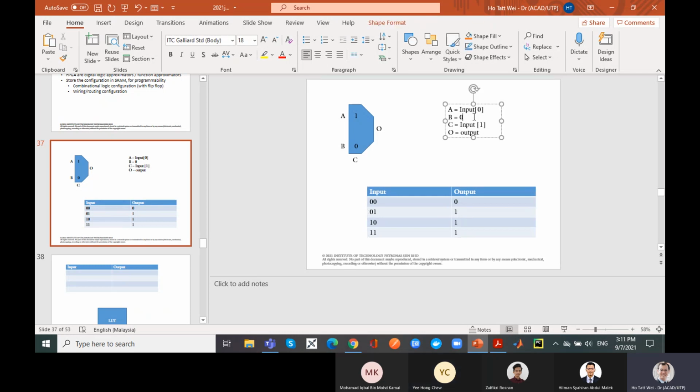Understood, huh? Okay, in the same way I can do it for an OR gate. And here is the same thing, except that maybe this is input 0, and this is definitely 1, something like this, okay? So I've just shown you how I can create the 3 basic logic gates AND, OR, NOT using a multiplexer. Therefore, we have said before, I think this is something you've covered in digital electronics, if you can implement AND, OR, and NOT, you have these 3 functions, you can implement any digital logic, any